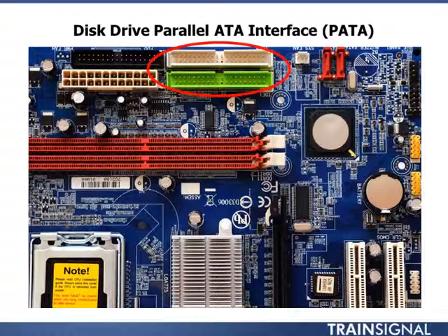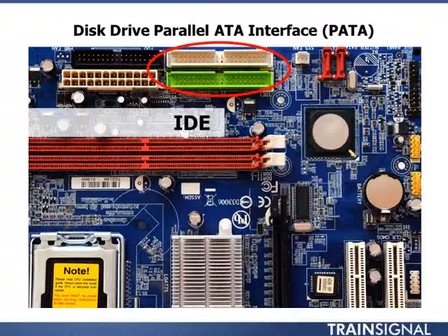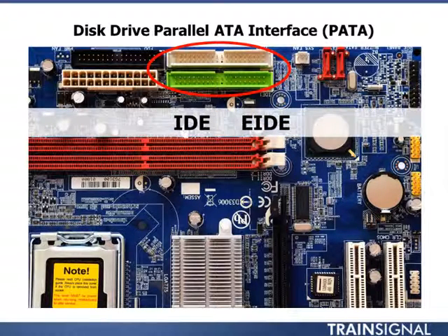One is called the ATA interface, which has been around for a long time. This is sometimes now called the parallel ATA or PATA connectors. And there are a number of different types. You have ATA1, which is also called just IDE or Integrated Drive Electronics. And you also have enhanced IDE, which is version 2 of the ATA, and this uses a 40-pin cable for data connection. And ATA controllers typically use a master-slave type of relationship.